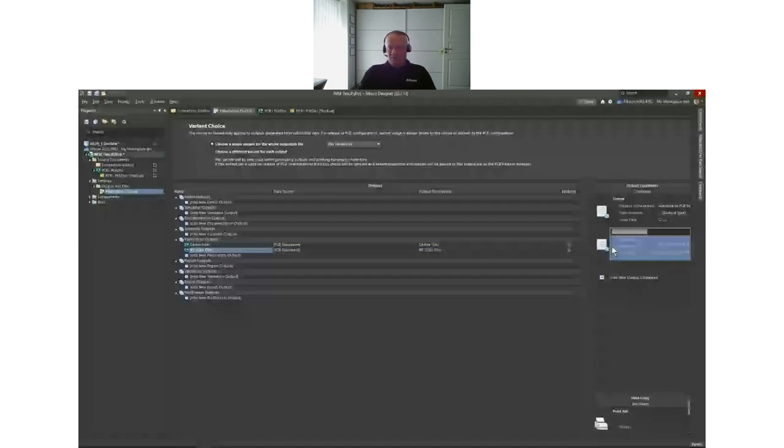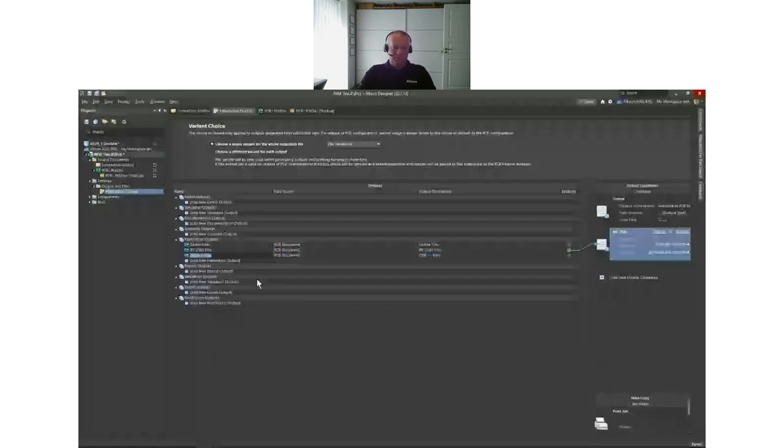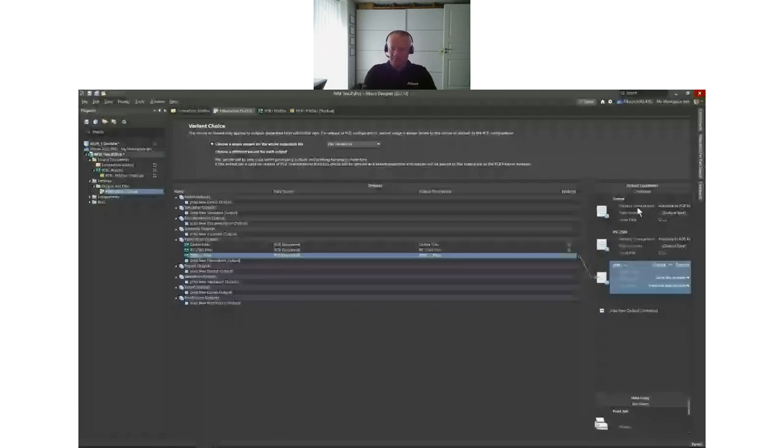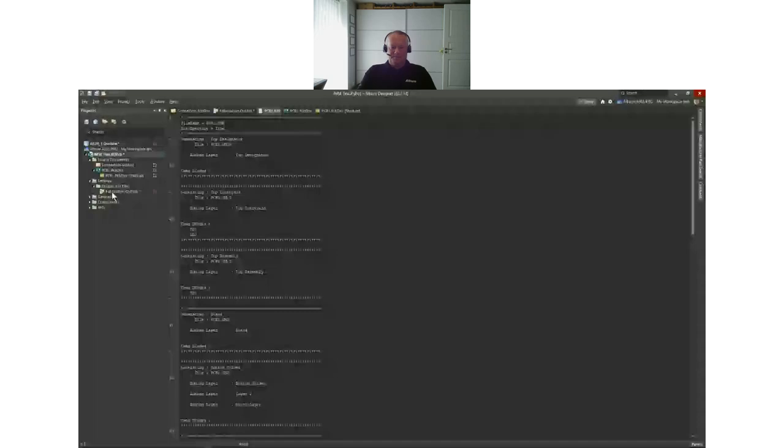I can also add IPC-2581. That is also possible. So let's add IPC-2581 like this. Or ODB++ files can also be generated, like this. Let's try and generate the Gerber so that you can see what it's like.